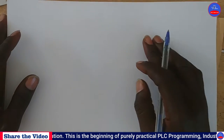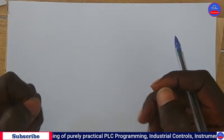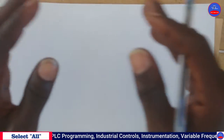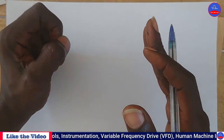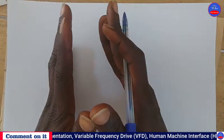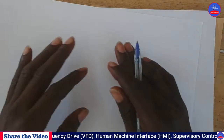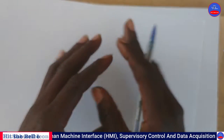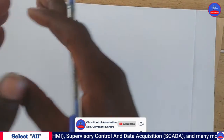So engineers, when we talk of an autotransformer, an autotransformer is a single winding transformer that has both the primary and the secondary windings on the same winding. Before we begin with the power diagram and the control diagram, let's explain the autotransformer itself, and then later you use that scenario to design the power diagram.